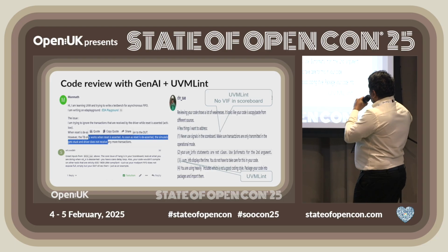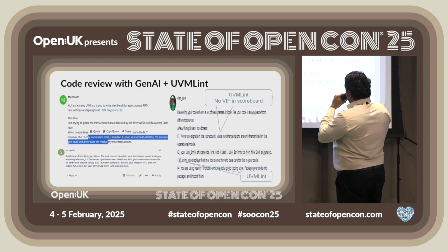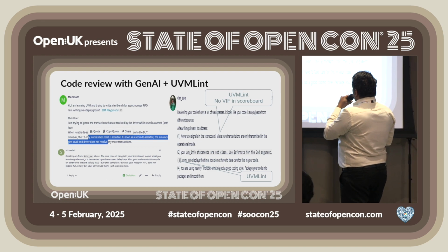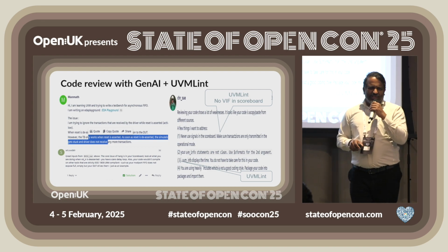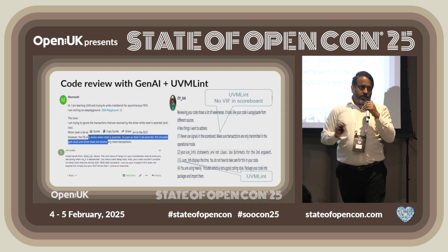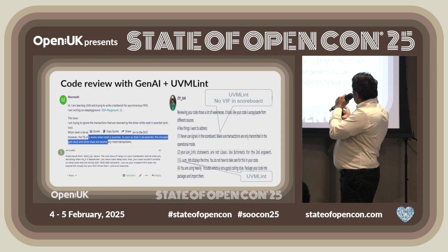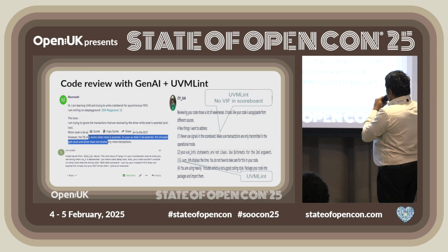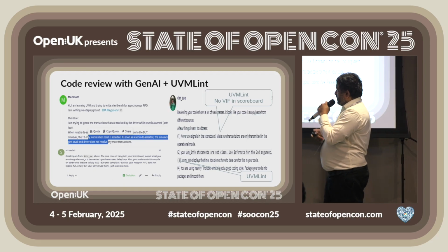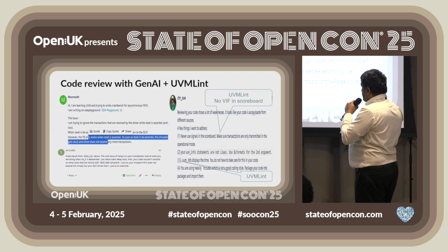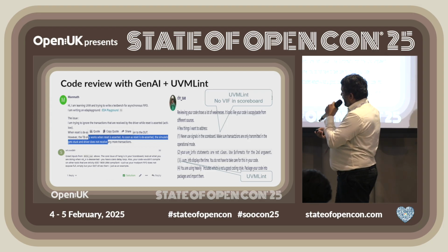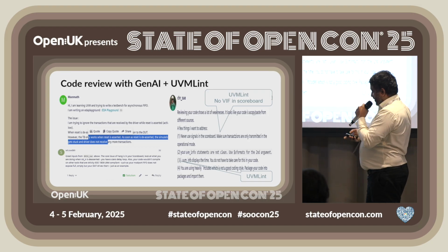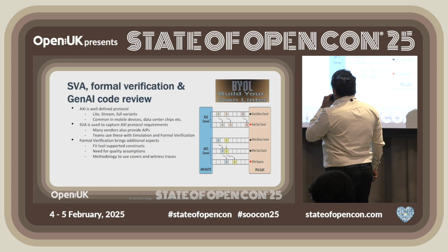So essentially there is a problem, and this is another gentleman who provides a lot of interesting stuff, and he says, let's not use signals straight in the scoreboard because that's known to be a problematic area. And that's what we have in the UVM lint. It says, do not use a virtual interface. That's one rule. And then for UVM info, you don't need a $display with time, and so on and so forth. So this is what I replied. This is my user ID. It hangs because you have a virtual interface which is not checking for the right things.